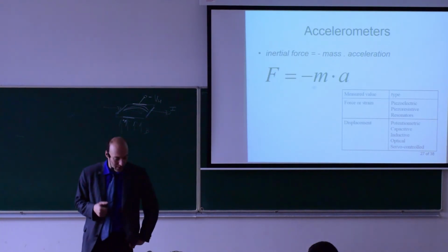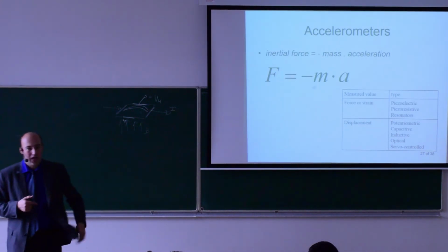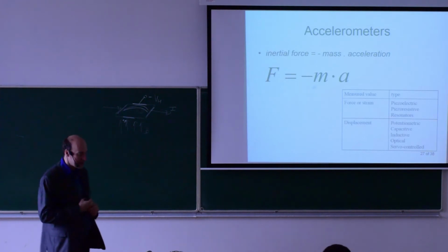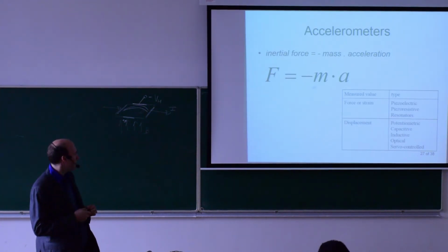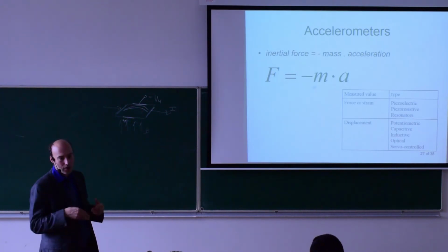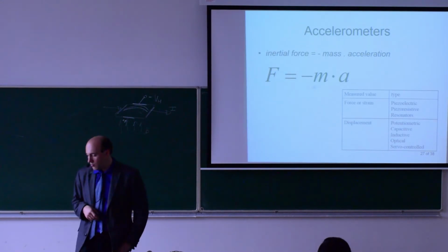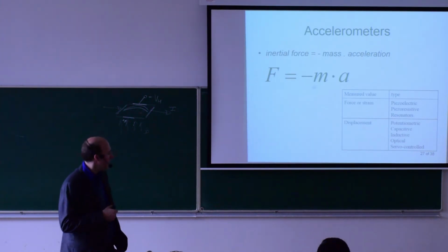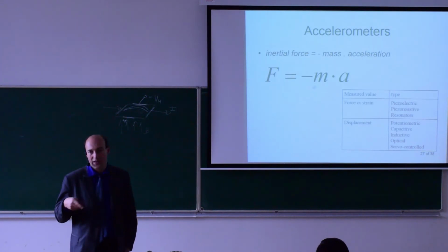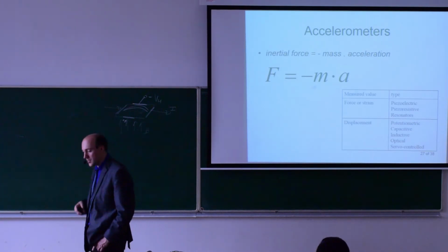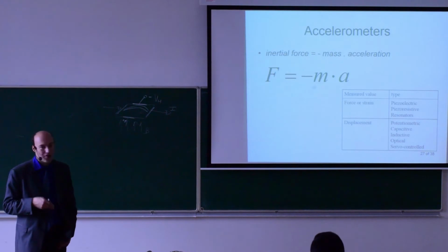Accelerometers, in most cases, do not measure acceleration directly, but we use the effect, the force that is created by acceleration. So we'll be looking for the inertial force that is created as the effect of acceleration or gravitation. There are many principles that you have here in the table used for accelerometers. We will discuss only one of them, the capacitive displacement accelerometer. It's the most common in applications like cell phones, airbag control, hard drive control, and so forth.